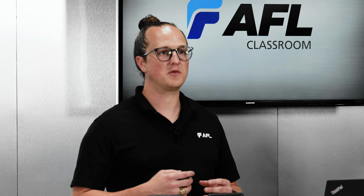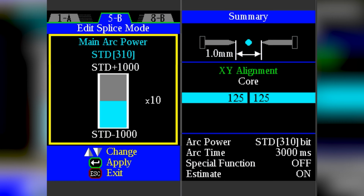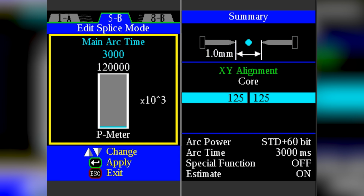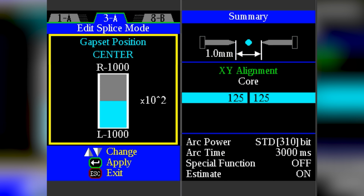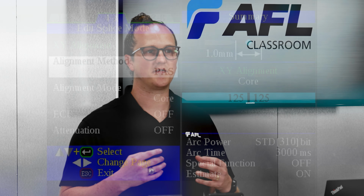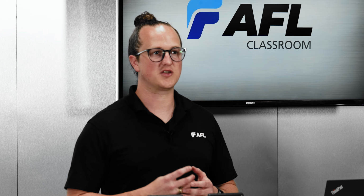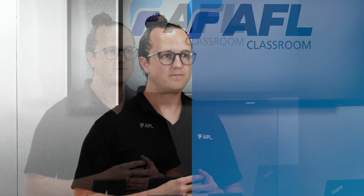When fibers having dissimilar mode field diameters are spliced together, there is a certain amount of baseline loss that comes from the dissimilarity. This mode field mismatch can be mitigated to some extent by extending the arc power or the arc time. Another option for very sensitive fibers is to explore the idea of changing the gap set position so that the smaller mode field diameter fiber is heated more than the larger. This promotes diffusion of the core dopants into the fiber's cladding, thereby expanding the mode field of the smaller fiber to more closely match the larger mode field diameter of the other fiber.